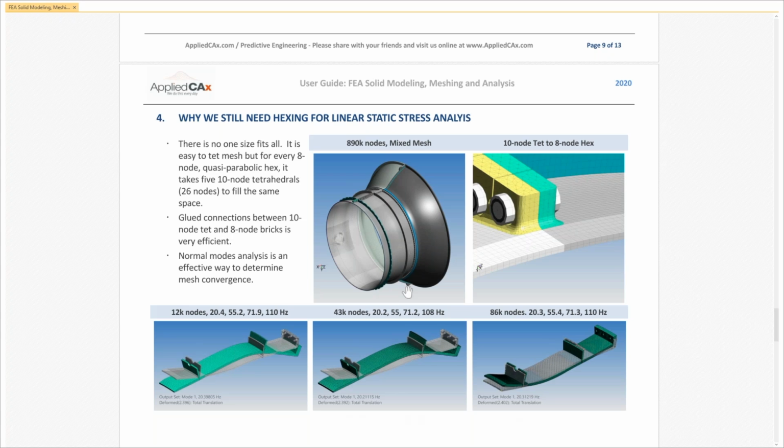I mean, yes, they're ordered within the TET, but you've got to think of a TET as just dumping them into a bucket, and the integration points are all over the place. Yes, if you use enough TETs, you get a smooth looking contour, but it's painful. Where with hexes, you come almost out of the gate with a nice look.